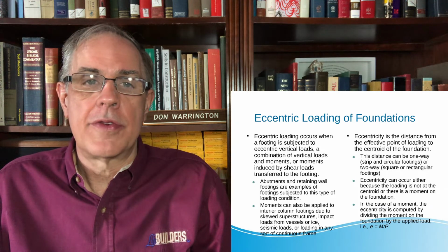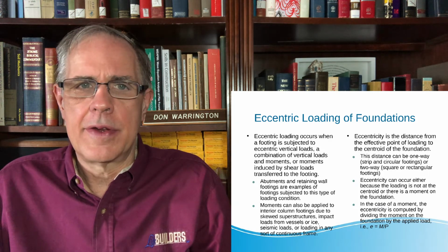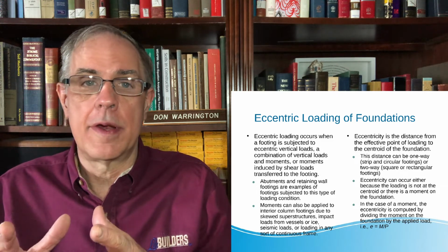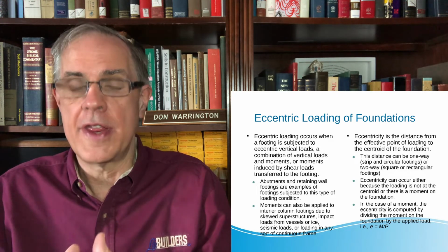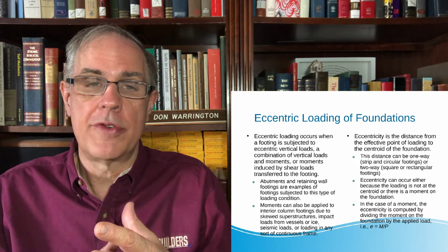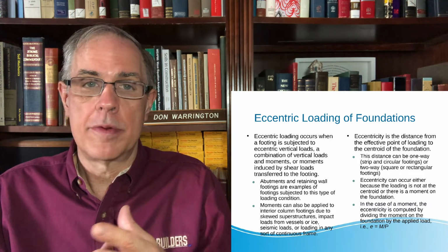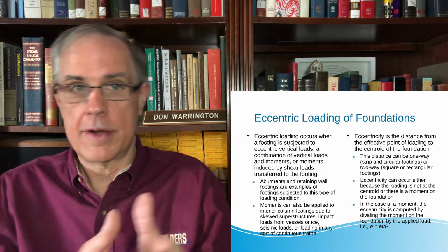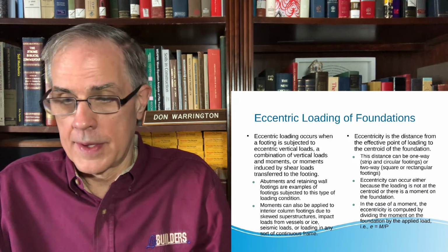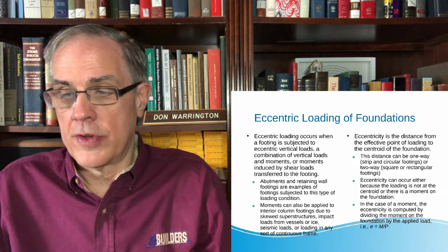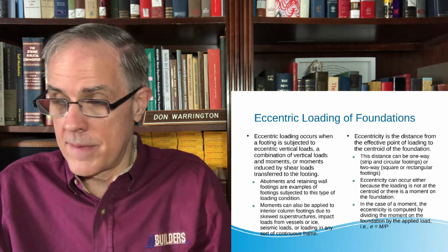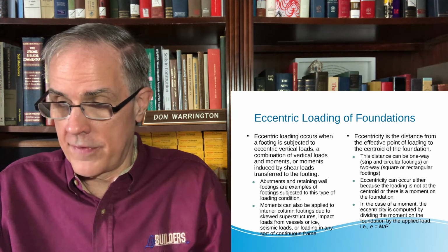Eccentric loading of foundations. Foundations are ideally loaded concentrically, but that's not always the case. If you're in a very tight situation with a footing and a property line, and you need to put the wall as close to the property line as you can get it, sometimes it's impossible for the footing to go over the property line, so it has to come back, so you get an eccentric load. Eccentricity is defined as the distance from the effective point of loading to the centroid of the foundation.